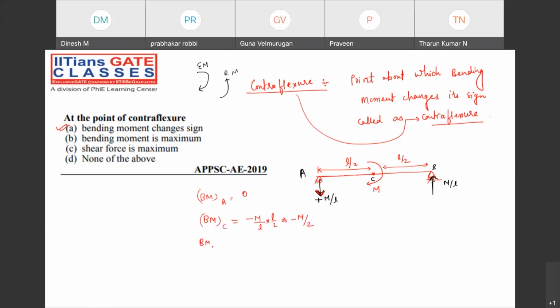Two times or one time calculation? Tell me, guys. Follow the conclusion. Why one time? When there is a concentrated load, calculate shear force two times. Whenever there is a concentrated moment, calculate the bending moment two times. I said already. Check it out.